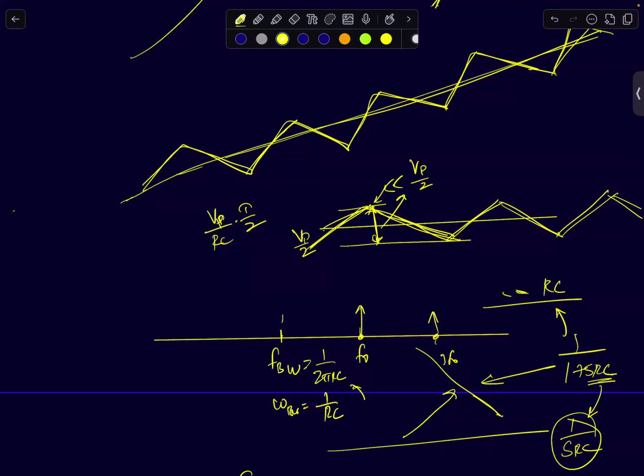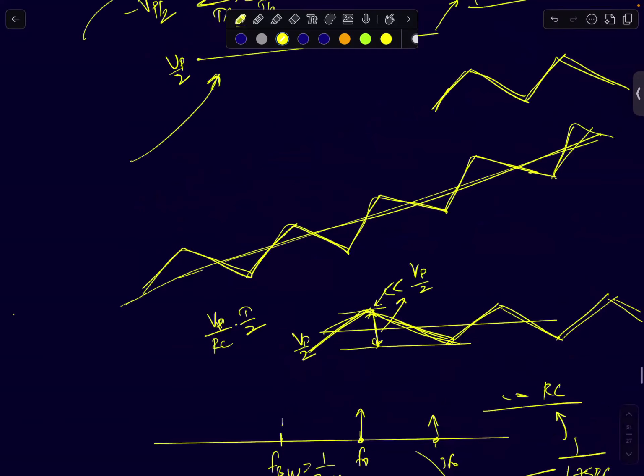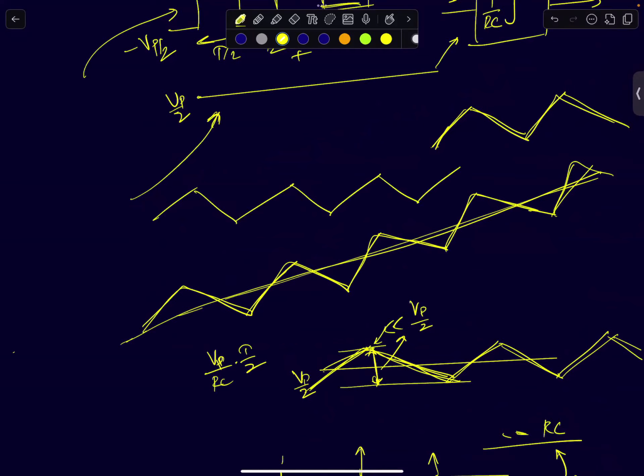But you should keep in mind the DC content of the input is slowly charging your capacitor. On every cycle, it is going through positive and negative charging due to this high frequency signal, and it is also getting small incremental charges every cycle from the DC signal. The DC signal is slowly dumping some incremental charges, which is what leads to this ramp rise.